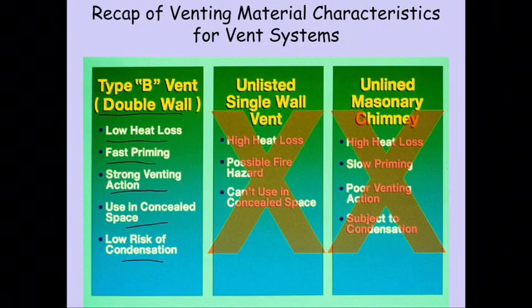Your single wall vent pipes have much higher heat loss. The fire hazard due to the clearance from combustibles has to be much higher. In fact, it's generally 6 times the amount, so that's fairly significant. And then, of course, they will never let you use that in between floors or ceilings or anything like that. That's against any code that would exist.